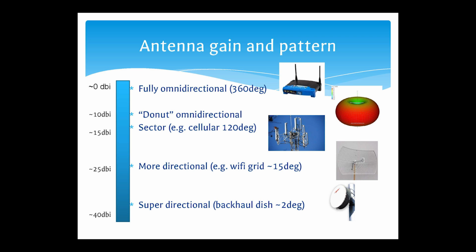Even higher gain than that, if you have a neighbor down the street and you want to steal their Wi-Fi, you can get a high-gain grid antenna. Those are often seen for longer distance Wi-Fi networking, and those have 24 or 25 dBi gain. Those focus the signal to about 15 degrees wide. So they do start to need to be aimed pretty precisely at the location you want to either send or receive a signal, so that you can get the signal you want where you want it.